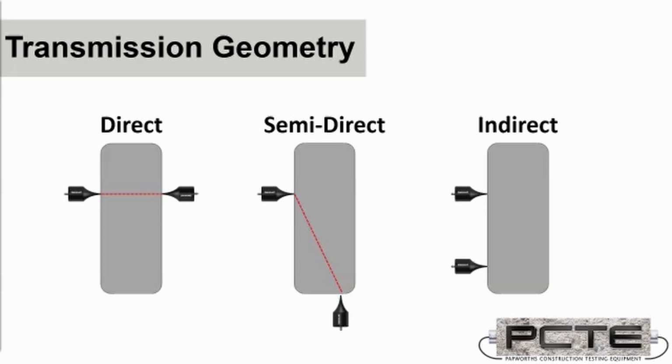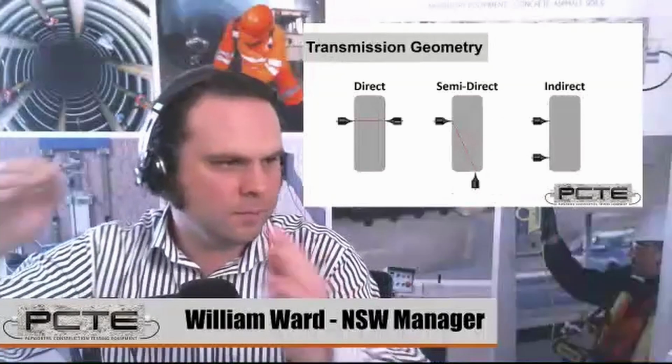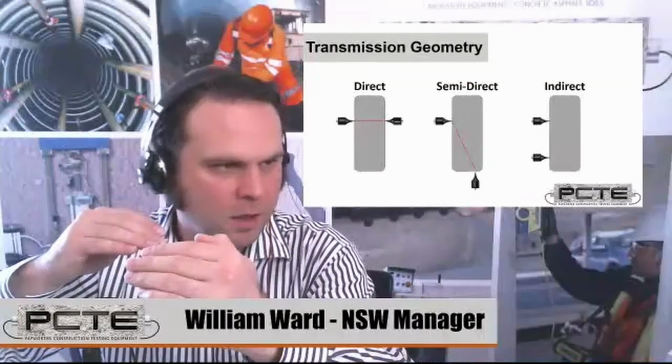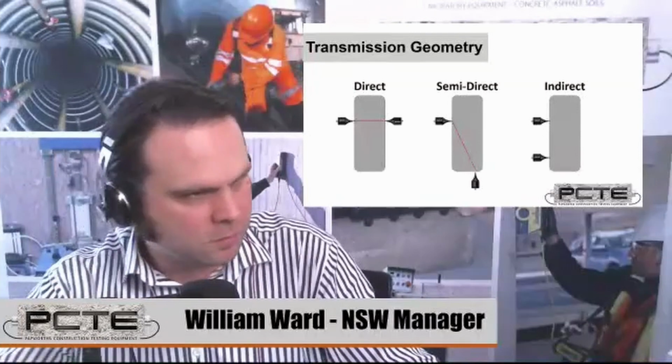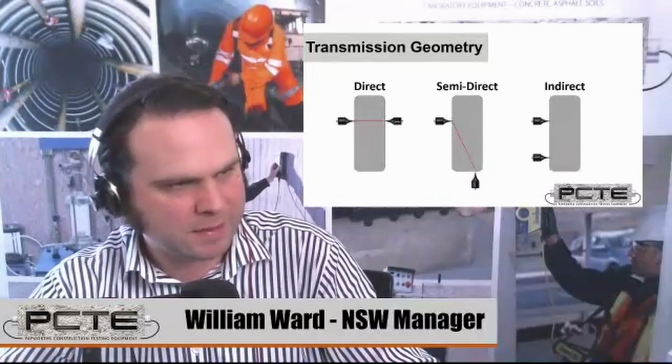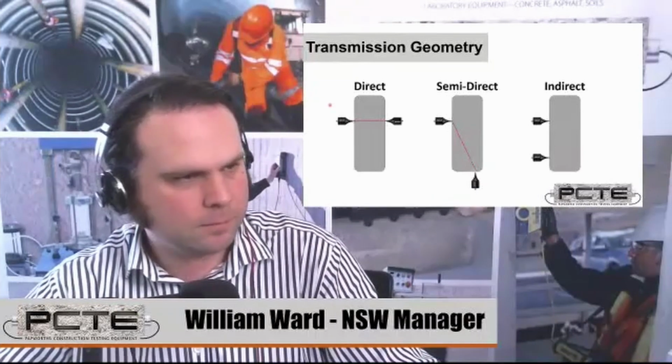We would also take advantage of this to align test areas. So we send our sound signals through the regions of concern, so through where we expect voiding might be. If you are testing a beam, you may move your transducers along that beam step by step, making sure a sound path has gone through all the regions where voiding might be expected.